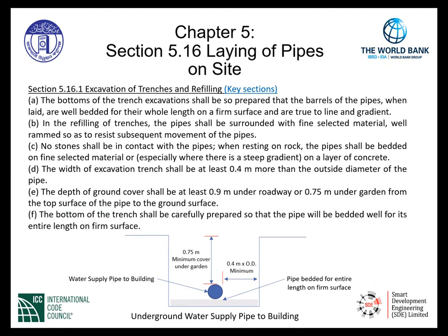Section 5.16, laying of pipes on site. This particular section gives us requirements regarding excavation, trenches, and refilling. Some key sections that we're going to learn about are given in section 5.16.1. Item A indicates the requirement that the bottoms of the trench excavations shall be so prepared that the barrels of the pipes, when laid, are well bedded for their whole length on a firm surface and are true to line and gradient.